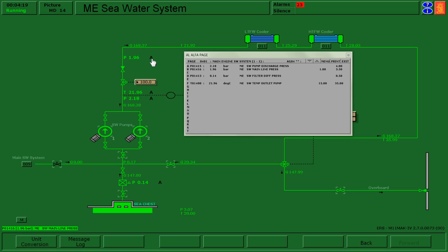Acknowledging as well, what you might do is start logging that. Depending on what plant you're at, they may have policies around logging alarms. It may be something that you have to note in the logbook depending on the severity of the alarm. And maybe something that if you have a turnover meeting to the next shift of workers, that you note that there were some alarms that came up in a certain area.